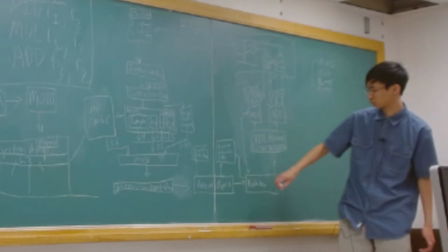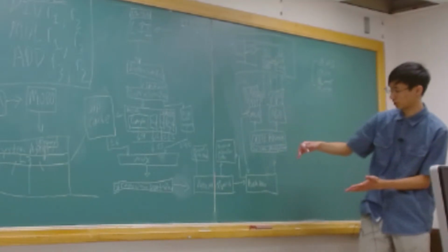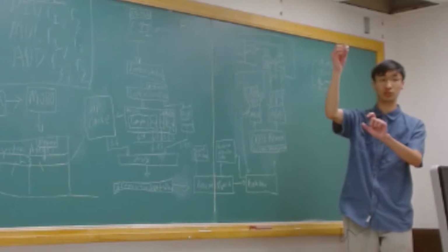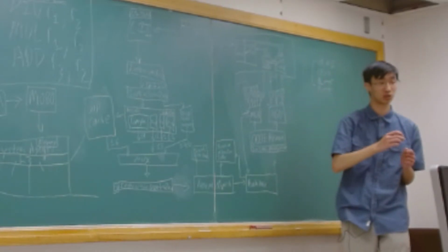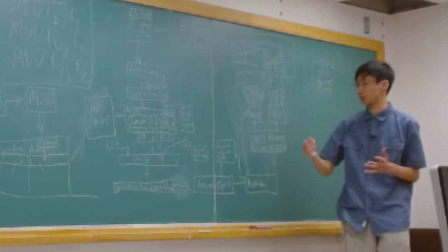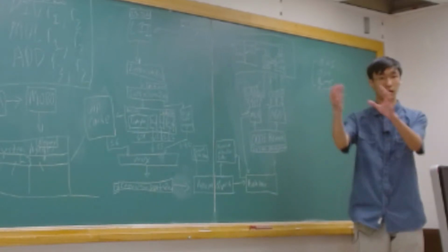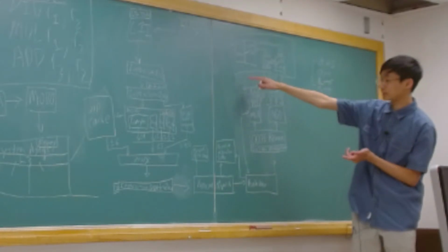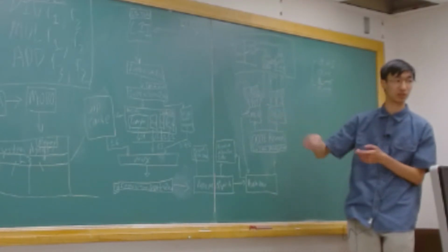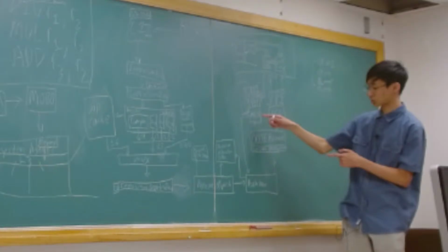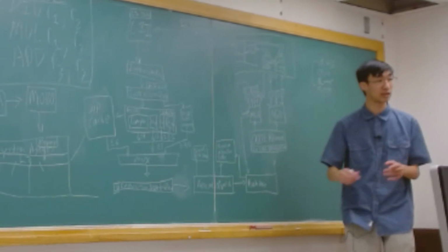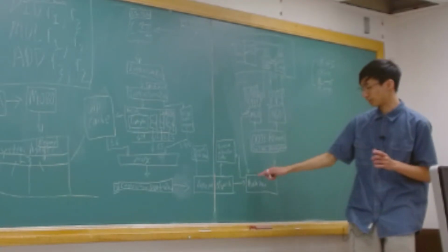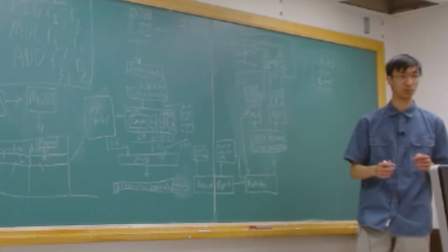And so there's a mess here, and let me talk to you about it. The first thing is, if you have two instructions, and the first instruction produces R1, and the second instruction consumes R1, that means that you have to be able to say, okay, I want to get that result from that, like let's say it goes through port 0. I need to get it back to myself. So I give it to the math scheduler so it can do it. And the math scheduler will say, okay, let's tell the reorder buffer that that instruction's done so we can free the resources that we use to track this thing. And then the reorder buffer will tell the register allocation table, okay, we're done with that register.